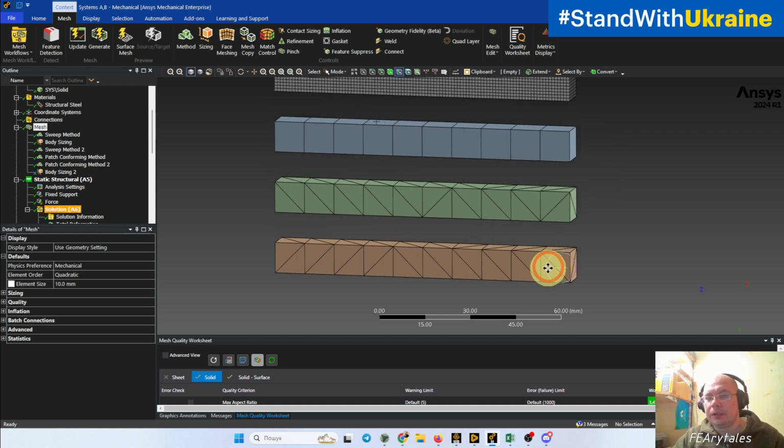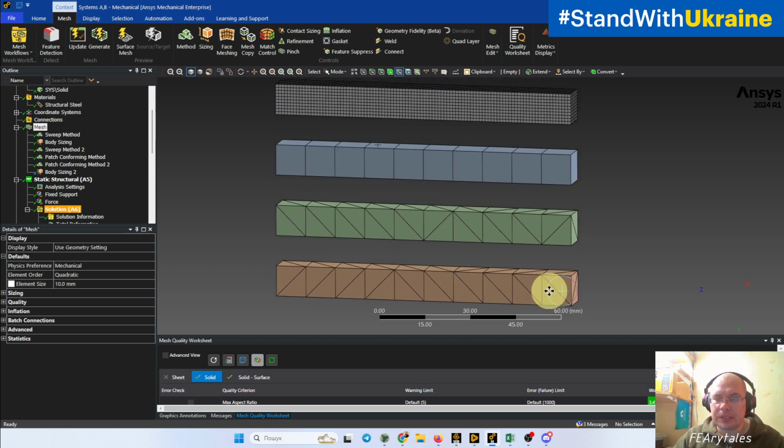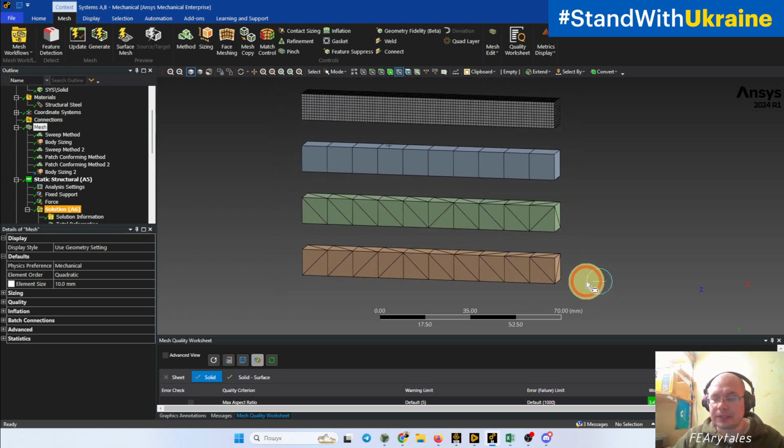But in 80% of tasks, and these are most cases, linear tasks with linear material behavior, this type of element, linear tetra, will provide very inaccurate results, and you need a very fine mesh to obtain a good solution.